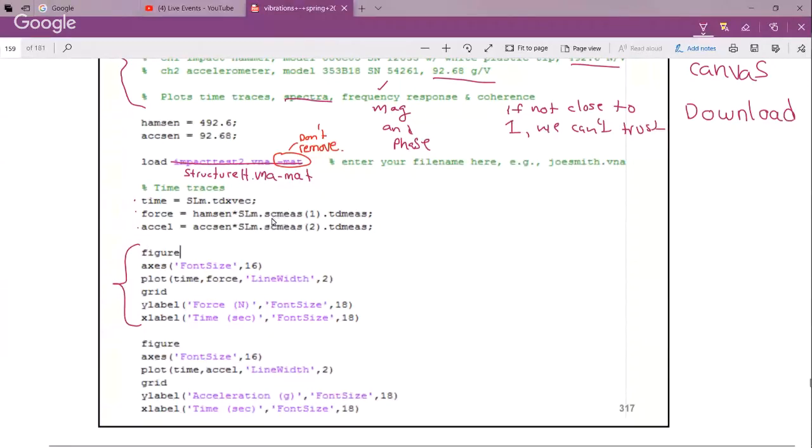I use ASP to denote auto spectra for both of the quantities. They're given in terms of volts, so I have to multiply by my sensitivity to get the proper units. That's why we have sensitivity defined.